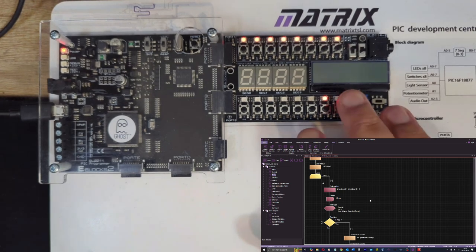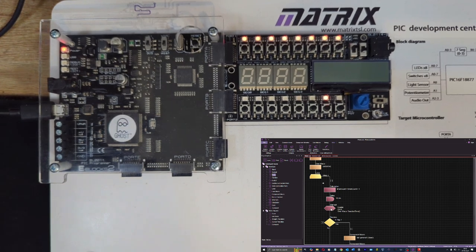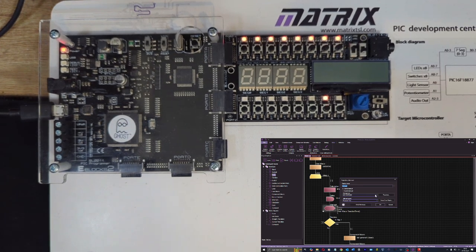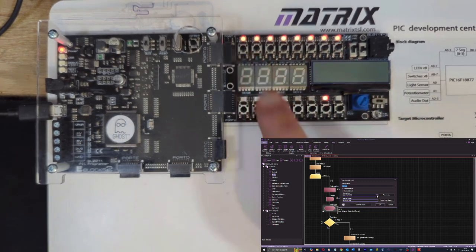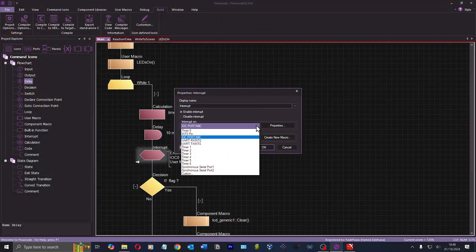At the moment, nothing's turned on the screen. The LEDs are all on. They should turn off after 6 seconds. They have not. They have remained on. What's my interrupt on? That's the question. There you go. My interrupt is on all of these pins. So let's change that. That will be certainly affecting things.